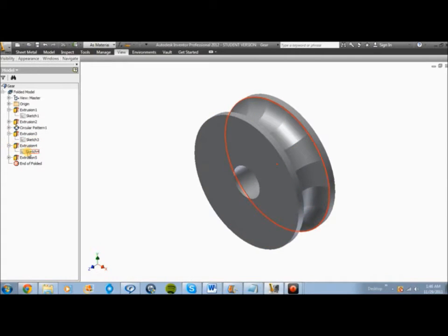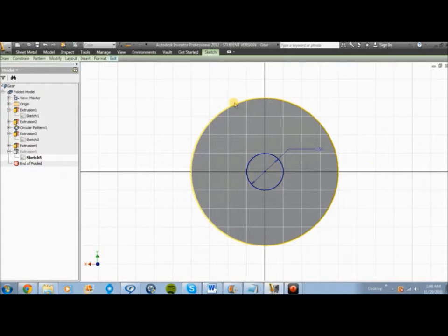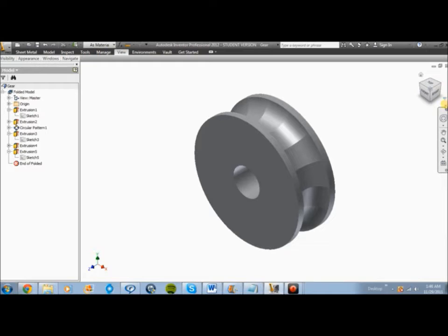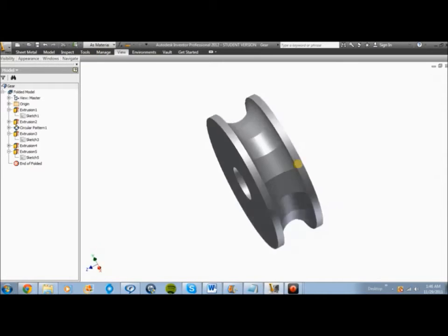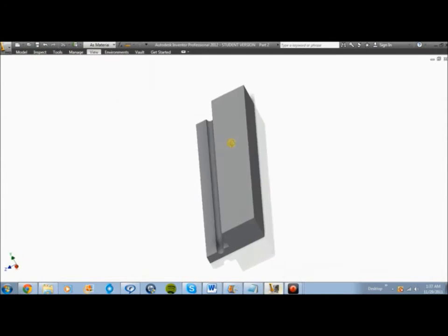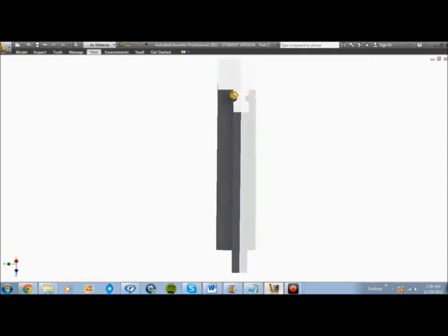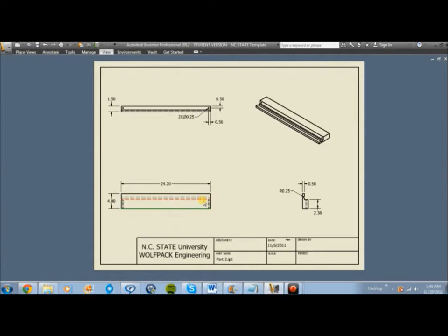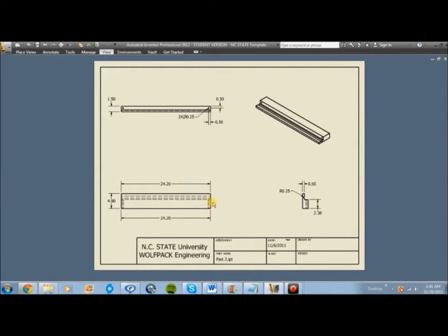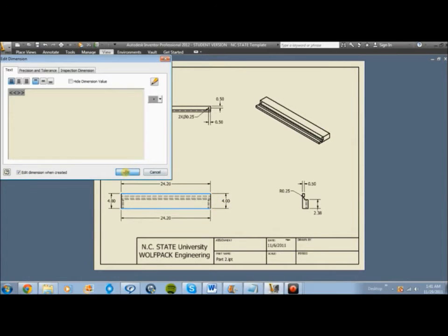The 2 sides were then 2D circle sketches that were later extruded with minimal thickness. Extruding means just making it into a 3D, as you can tell. And then later, the center hole was made by creating a small circle on a 2D sketch and later doing a cut extrusion throughout the whole part. As you can see here as well, we show our inclined plane and an orbital view in exactly each facet of the product. Autodesk also helps in creating working drawings in order to put dimensions on them that could later be used in manufacturing in order to create an effective and accurate product.